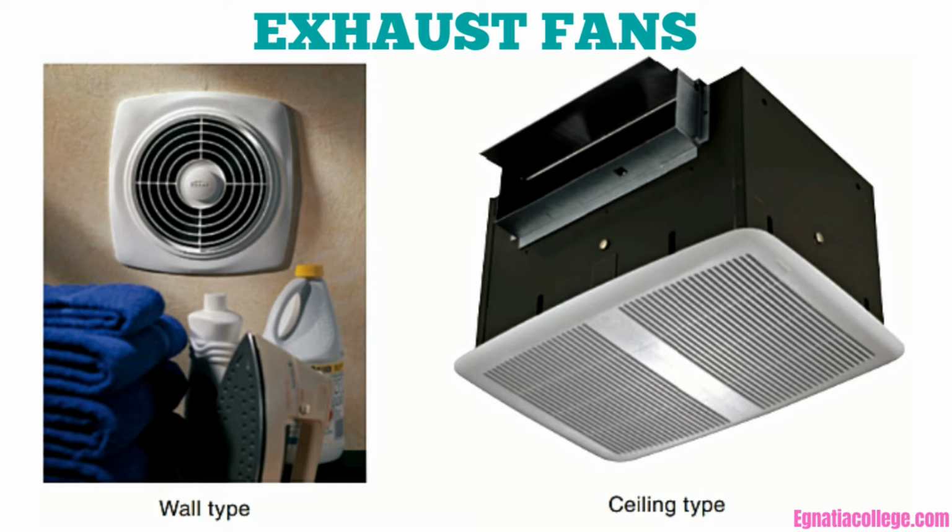Exhaust fans may be installed in walls or ceilings. The wall-mounted fan can be adjusted to fit the thickness of the wall. If a ceiling-mounted fan is used, sheet metal duct is recommended between the fan unit and the outside of the house. Any exhaust ducting located in an attic space must be insulated. During the cold season, any moisture that is removed by an exhaust fan will condense in an uninsulated duct. This will lead to premature rusting of the exhaust duct and fan. The moisture can also leak out of the fan or duct, causing serious water damage.